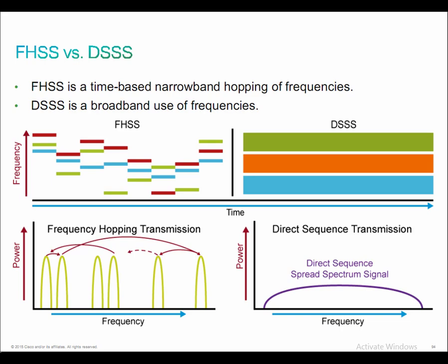Like I said, DSSS stands for Direct Sequence Spread Spectrum. It's a spread spectrum modulation technique, and again, like I mentioned on the previous slide, the goal here is to reduce overall signal interference. So the spreading of the signal makes that wideband channel more noisy, but it also provides for greater resistance to unintentional or intentional interference.